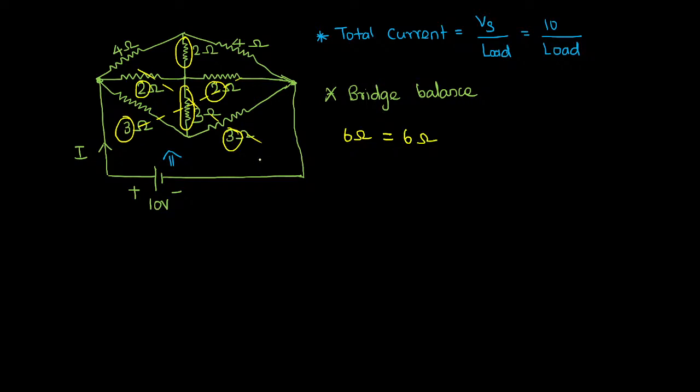Yes. So whether this bridge is balanced or not? Yes, sir. Load across cross arms, if you find the product of this cross arms resistance, and the value on both sides comes out equal, that is the concept of bridge balancing. So at that time, what will happen is the voltage existing at this point and the voltage existing at this point will be equal.